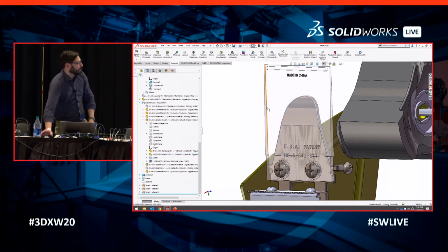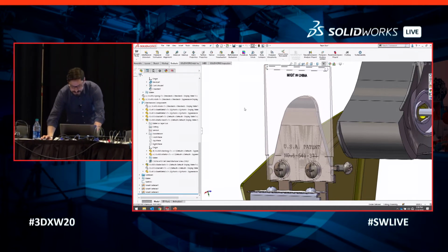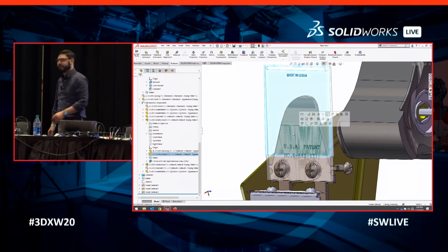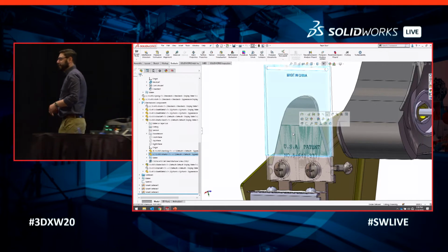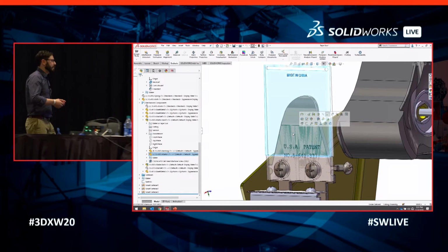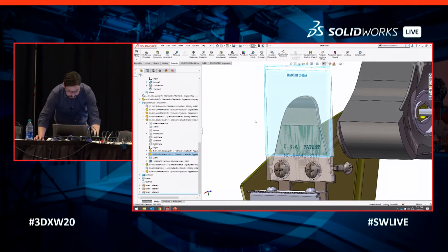But what if there's a whole bunch of parts under there and I can't do that? That happens to me all the time. And then I realize, oh yeah, I have to hit the shift key. Okay, so if you hold shift, it'll just grab the part that's on top. Okay? Kind of silly, but you know, it does save a lot of time if you can remember to do it. Okay.